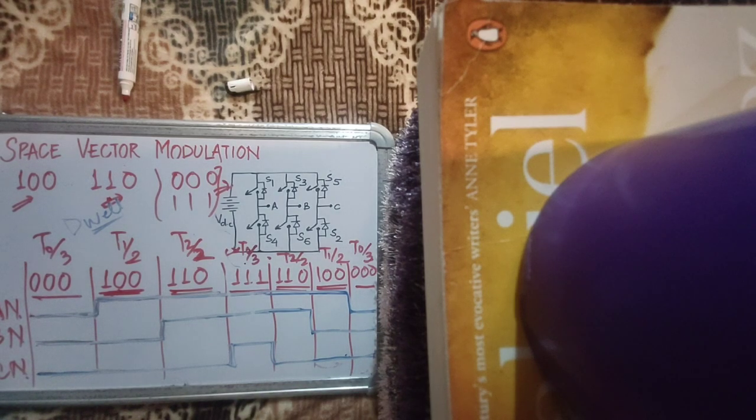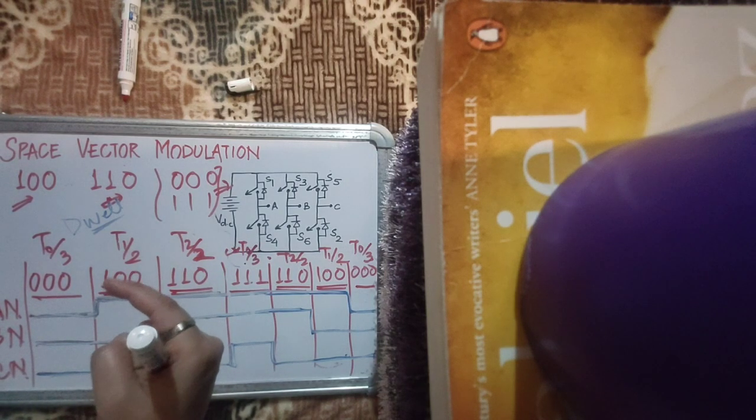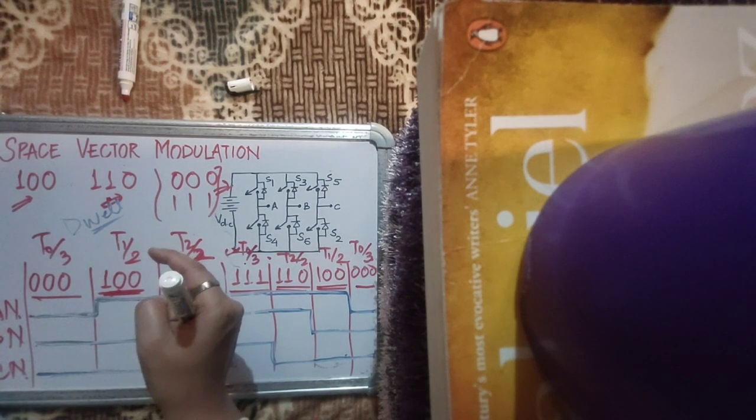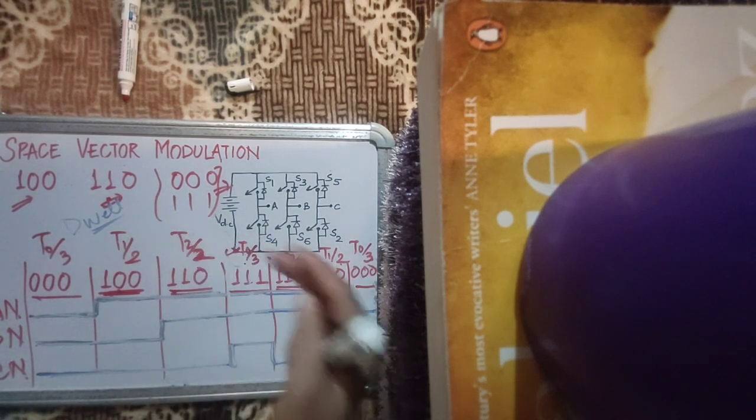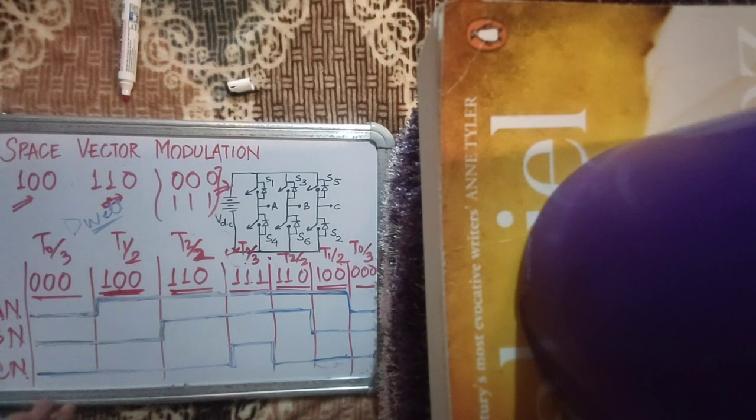So this was about space vector modulation. It gave you increased voltage conversion ratio from 61.2% to 70.7% just while maintaining your sinusoidal output, while maintaining a good harmonic performance. Second, you can rearrange your dwell times in such a way that you get waveform symmetry and therefore you can increase the harmonic performance further.